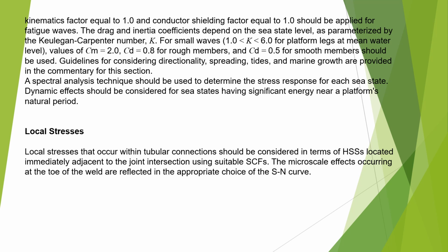Here we could see one more thing also. Spectral analysis techniques should be used to determine the stress response for each sea state. So for each sea state we need to get the stress response. Dynamic effects should be considered for sea states having significant energy near the platform's natural period. So if the sea state has sufficient energy near the platform natural period, if the platform natural period is say around 1.2 seconds, 3 seconds, 2 seconds, something like that, and the sea state also has sufficient energy, then dynamic effect should be considered.